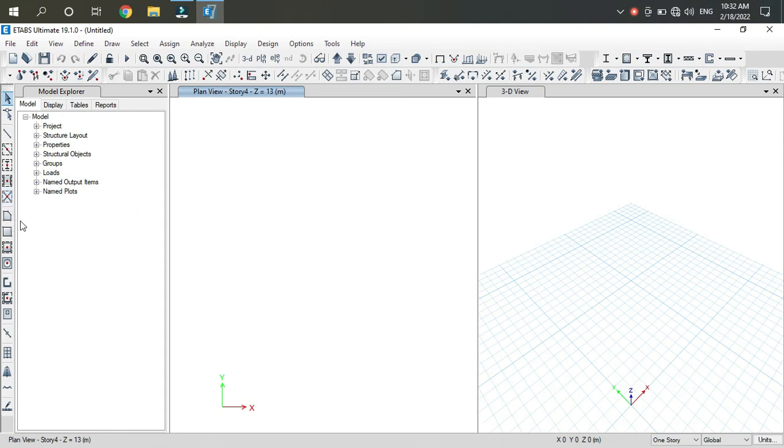This is for the braces and this for the floor or wall. This is the floor walls and this is the slabs. Then area around point, and the draw command. We can draw walls or we can also quick draw walls, which will automatically draw walls, right? For the shear walls, if you want to draw any wall openings, draw plan links, draw wall stacks, design strips, design end points and slab rebars.